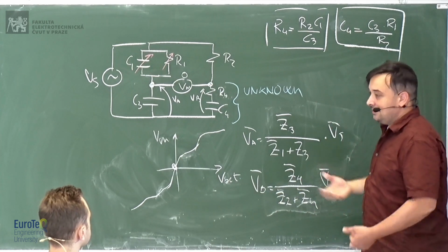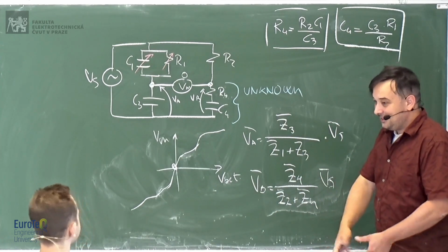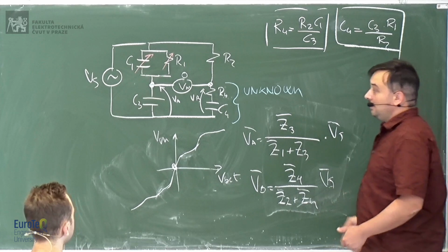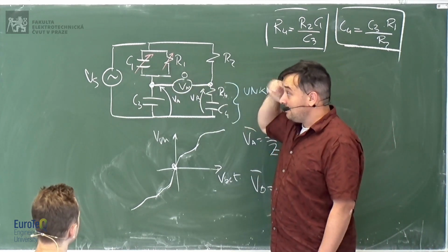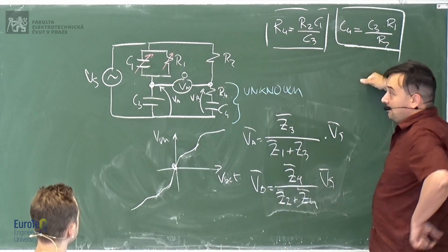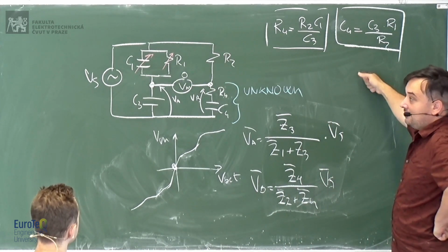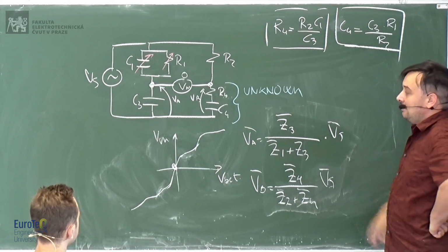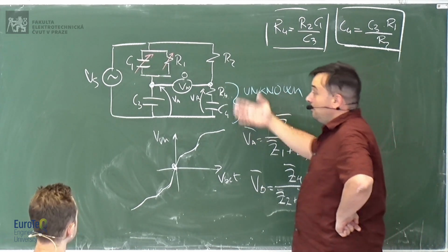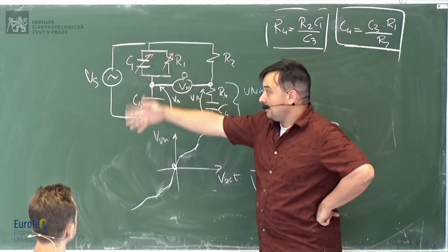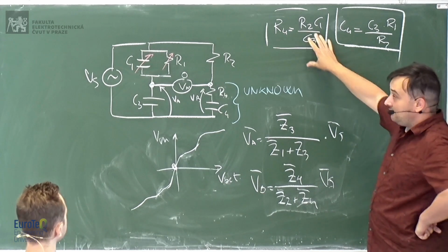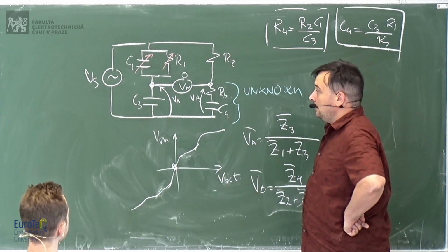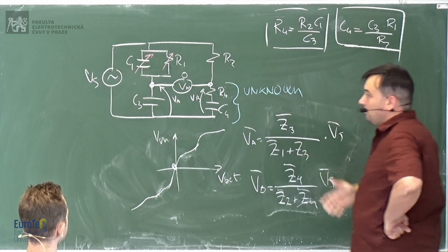Now, if you do it manually, the speed of measurement is the speed that you have. You can do it automatically. So what you can do is to measure here the voltage, and then an automatic system can adjust this capacitor and resistor. But again, it's not as fast as measuring a voltage out of an operational amplifier and then recalculating the impedance. So you can use this system if you want some very precise measurement where you cut away all sort of uncertainty, and you're left with this uncertainty, which depends only on the components, okay? And you can have some good components.